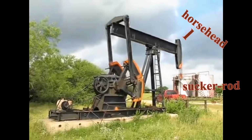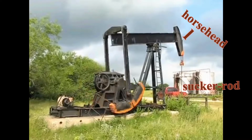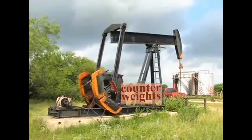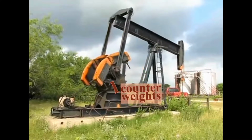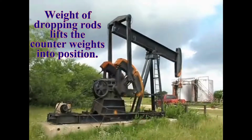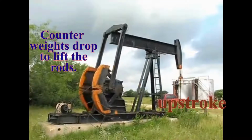The sucker rods are attached to the horse head that now goes up and down as it travels in and out of the hole. The counterweights located here distribute the power evenly over the up and down strokes. On the downstroke, the weight of the dropping rods lifts the weight into position, and then on the upstroke, the weight drops, lifting the rods and fluid column.